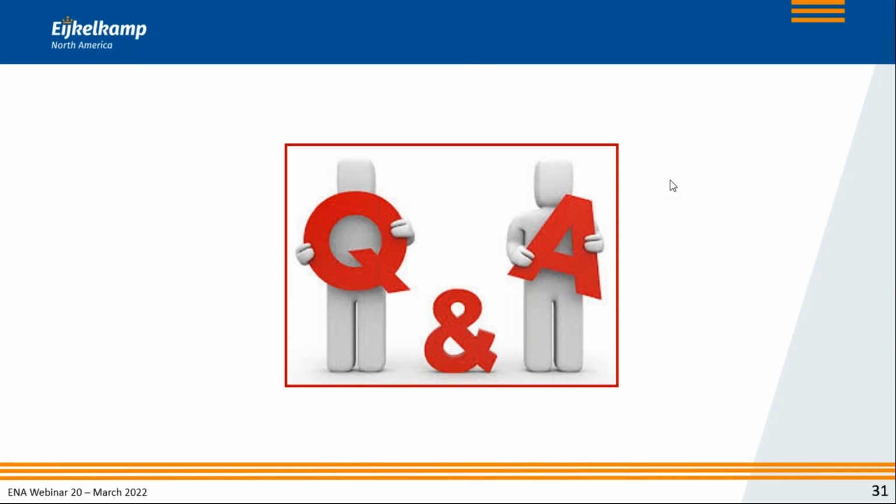The second question that came up was that the increase in your tip resistance as a result of deep compaction may be due to secondary settlement, creep, or simple rearrangement of the soil structure.